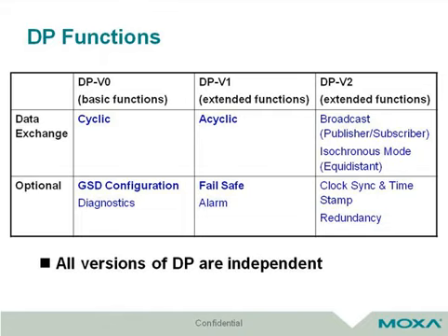The slave-to-slave communication function allows Profibus slave devices to listen to the actual values of other slaves and use these as set points. A slave device which provides its actual values to other slaves is called a publisher. Devices which listen to the actual values of other slaves are called subscribers.